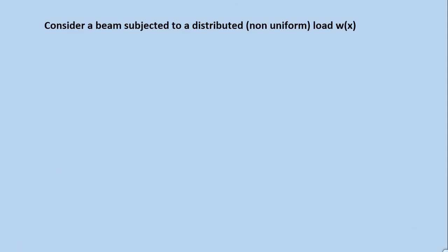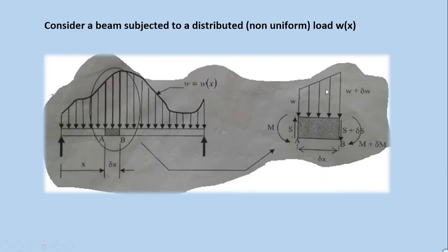This whole expression is due to the moment created by the external distributed load. In this case, in these two portions, we have divided this distributed load into two sections. When we draw a line here horizontally, you see that this is a trapezoidal load, so we can divide it into two.